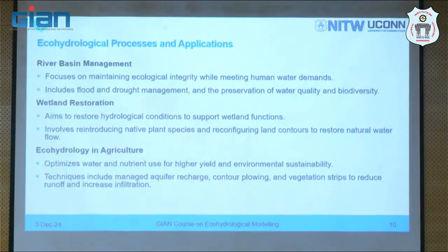And so the dissolved nutrients will get into the subsurface zone and not get into the stream right away. Because it slows down the runoff, it will promote deposition of sediment, and sediment-attached pollutants will not get into the stream, and therefore the health and quality of the stream is protected. The whole concept of ecohydrology at work.